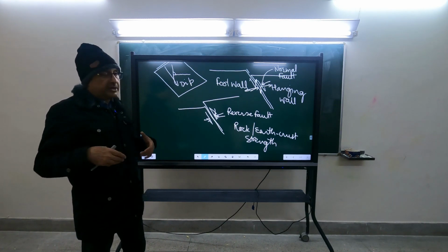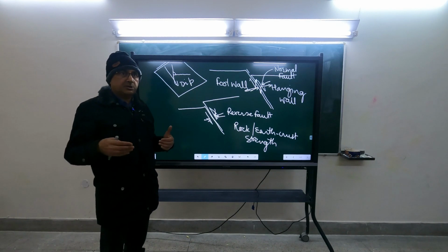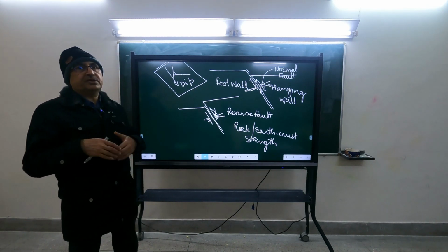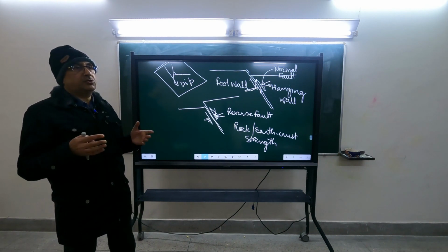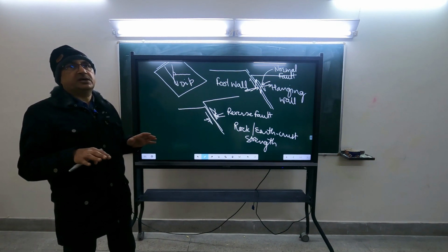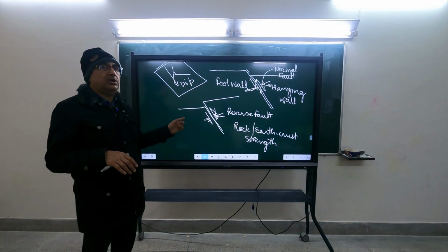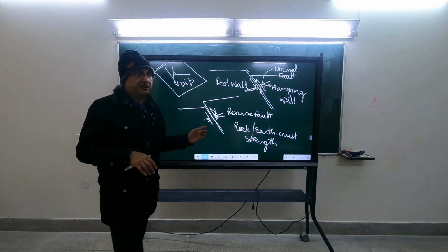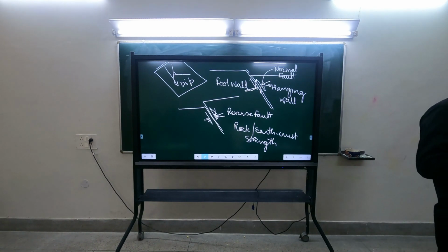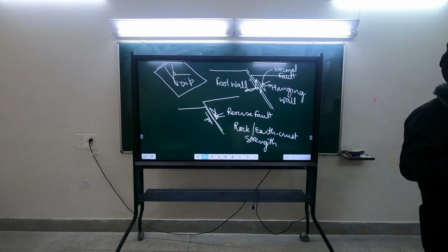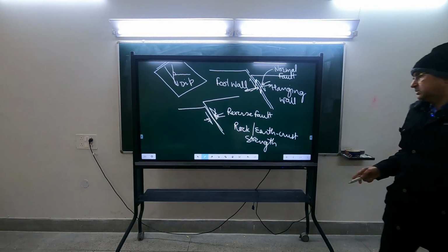The tectonic plates within the crust of the earth are moving with different speeds in different directions. So that's why the pattern of earthquakes is different. Different faults are behaving differently, so each fault needs to be characterized. Characterized means what maximum magnitude can occur and what is the source mechanism at which it is occurring. So that needs to be known.